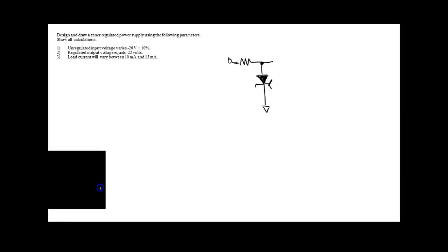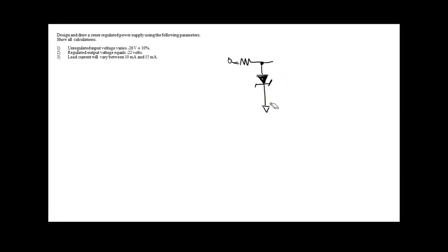If you don't exceed the breakover voltage, it acts just like a diode. It's when you exceed that breakover voltage that it acts like a Zener, right? You understand? If you break over a Zener, it's not going to burn up if you choose the right resistor. If this was a regular diode and you broke it over, it'd be gone. So it's designed to operate in the reverse breakover, but when it breaks over, we've got to protect it with that resistor, right? You understand?